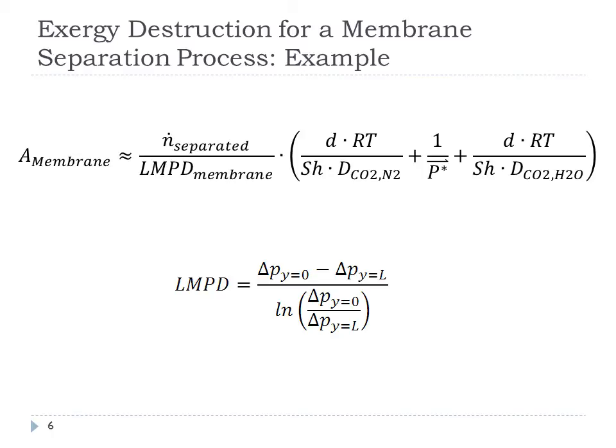and then when you're in the turbulent regime, it's going to go like the Reynolds number times the equivalent. This time it's not the Prandtl number, but there's another equivalent non-dimensional number that we'll be covering. And then we're going to be dividing by the diffusivity, right? So resistance decreases as the diffusivity increases. So that's the resistance on the feed side.